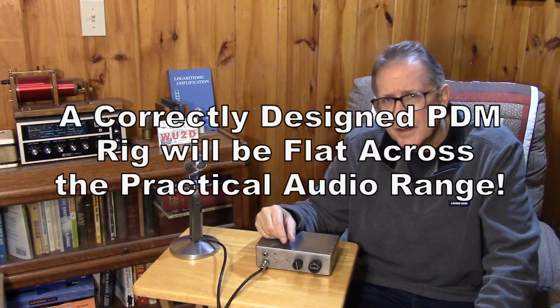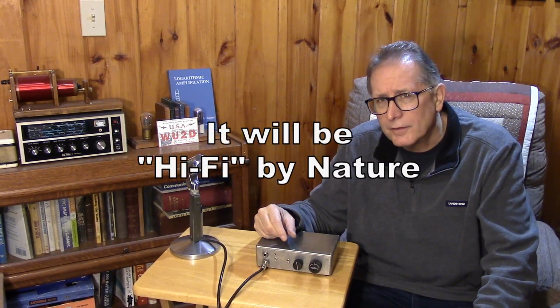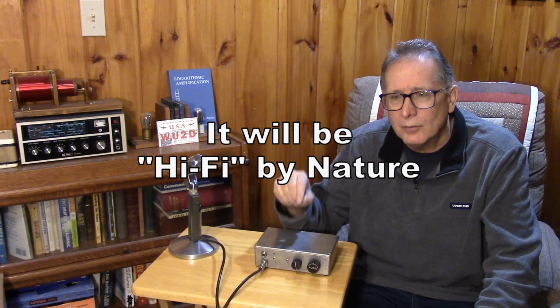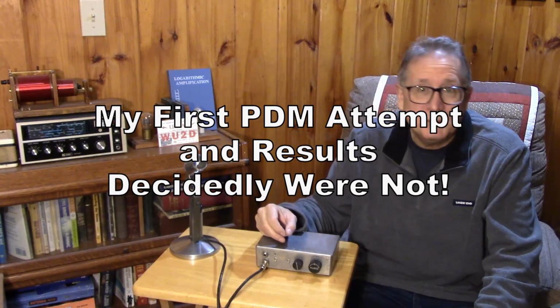There's going to be some clipping involved, and by clipping I mean negative peak clipping, and we're going to learn about soft clipping versus hard clipping. And also we're going to be doing a little bit of equalization, that is fixing the audio response so that it works better with the transmitter. We know that the transmitter doesn't seem to have a flat audio response to the human voice. Let's fix that with an equalizer. So this is all about speech processing. Welcome to Speech Processing, Video 1.